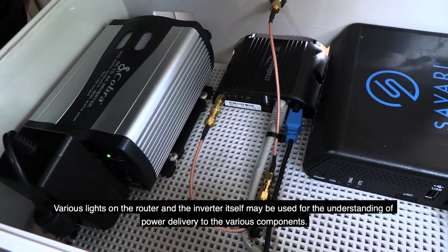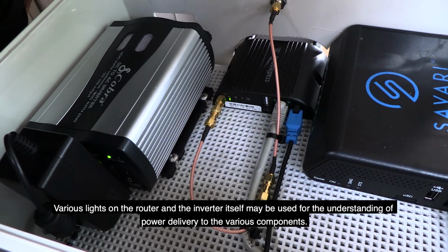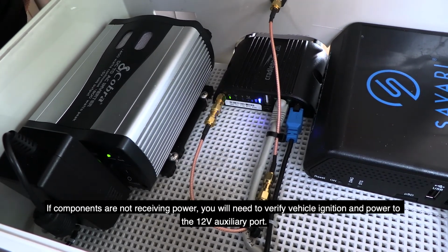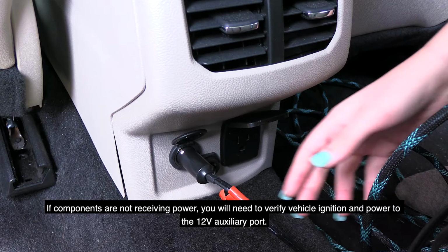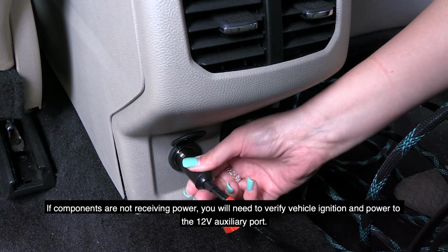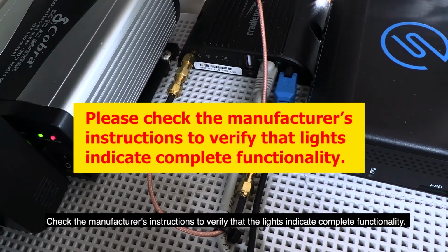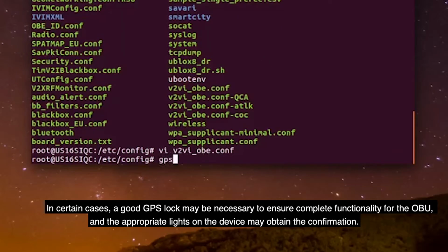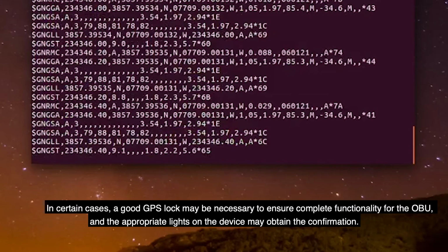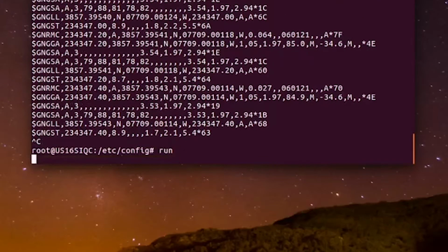Various lights on the router and the inverter itself may be used for the understanding of power delivery to the various components. If components are not receiving power, you will need to verify vehicle ignition and power to the 12-volt auxiliary port. Check the manufacturer's instructions to verify that the lights indicate complete functionality. In certain cases, a good GPS lock may be necessary to ensure complete functionality for the OBU, and the appropriate lights on the device may provide the confirmation.